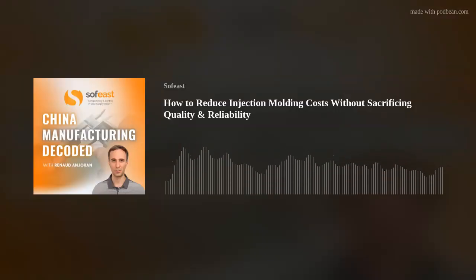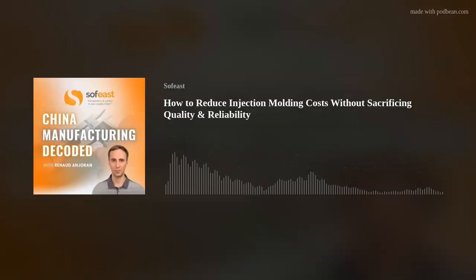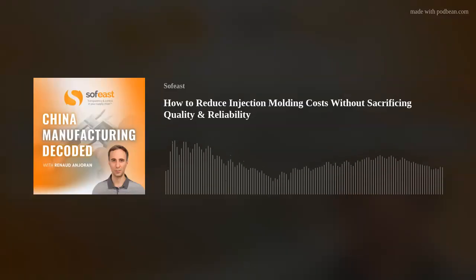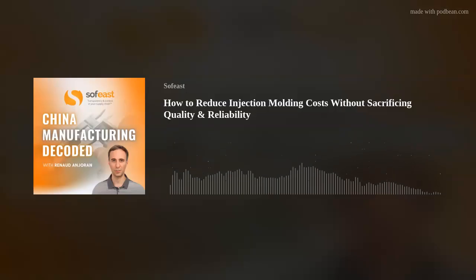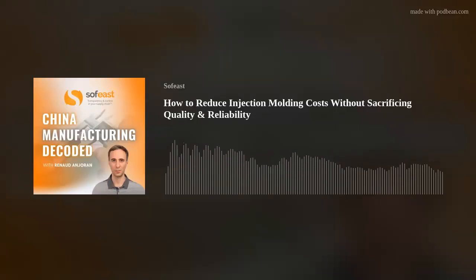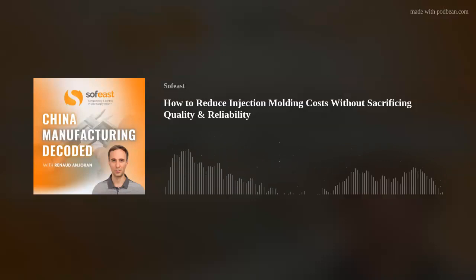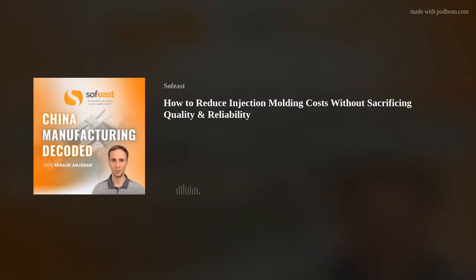Okay, so with these little tips and tricks, you need to make sure that your mold maker is not saying, well, this batch, the price of your parts went up. That's not really looking at reducing the cost of the tooling, but this is just a free tip, let's say. It's really all about matching up the size of the tool to the tonnage of the machine, as opposed to, well, we've only got a 400-ton machine available to run your 10-ton optimized machine tool. It can be done, but it's not ideal.